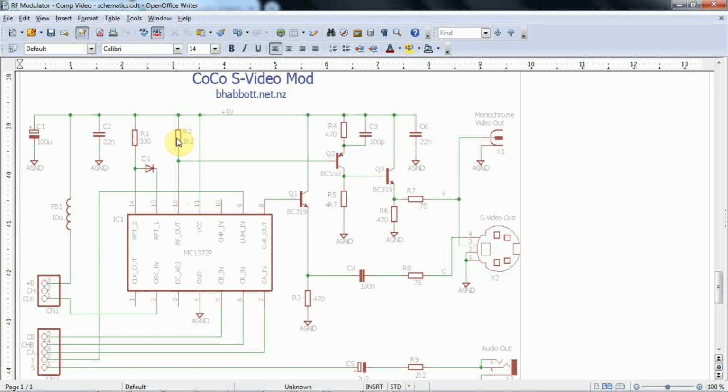You can send that to one monitor, and you can also at the same time drive a second monitor with S-Video, and the two circuits do not load each other, and there's no dimming of either picture. Now you'd probably never really benefit from having two copies at the same time, but this is just the way that I chose to implement it in my mod, because I already had a circuit to make composite video on pin 12, because that came from the 6847 data sheet, and then I wanted to separately try an S-Video mod over here based off of just pin 8 and pin 9. I'm going to show you that in a minute.